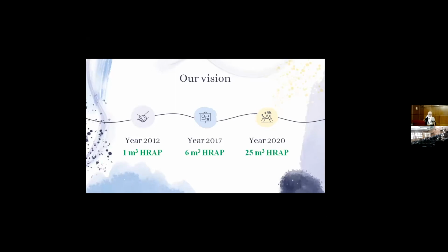And the team of Dr. Galina began in 2012 to upgrade this system. It was constructed, as we mentioned before, with the anaerobic pond, followed by the facultative and the maturation pond. The maturation pond is converted to the high-rate algal pond with another depth. The maturation pond was 1.5 meters deep, but the high-rate algal pond is only 0.5. In this system, the team produces algae and treated wastewater.